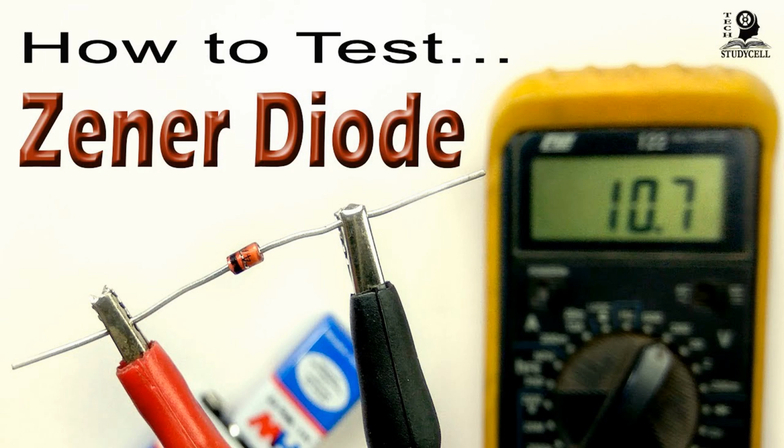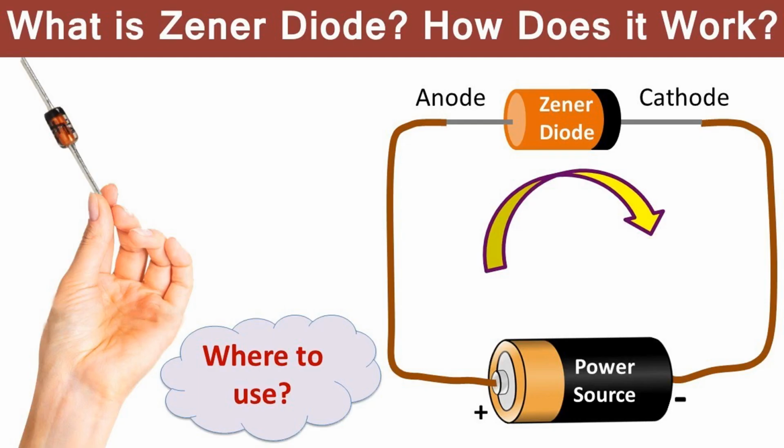Voltage dividers. Voltage dividers are simple circuits consisting of resistors used to scale down voltage levels for measurement purposes. They are commonly employed when the voltage to be measured exceeds the range of the measurement instrument. Data acquisition systems, DAQ systems, are used for automated voltage measurements in various applications. They consist of hardware modules and software that can acquire and record voltage data from multiple points in a system simultaneously. Voltage sensors. Voltage sensors are specialized devices that can measure voltage levels and provide analog or digital outputs.